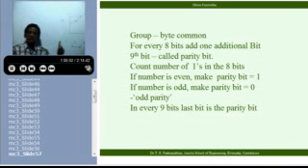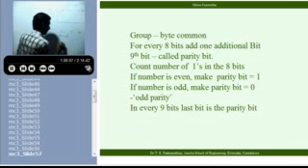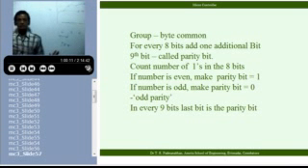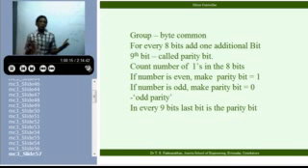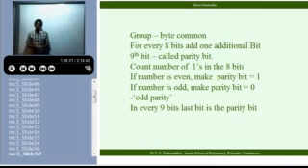Any noise, corruption or pickup that is limited to plus or minus 0.5, I know that this is the value. If it exceeds 0.5, you have no way of retrieving the original data. But if you are sure that your corruption will be limited to 0.5, you have got your original data.